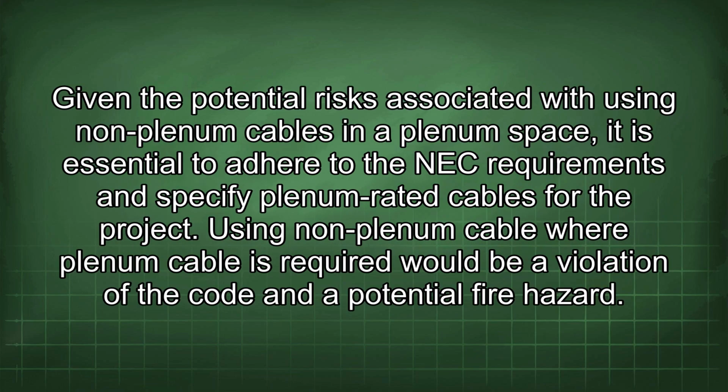Given the potential risks associated with using non-plenum cables in a plenum space, it is essential to adhere to the NEC requirements and specify plenum-rated cables for the project. Using non-plenum cable where plenum cable is required would be a violation of the code and a potential fire hazard.